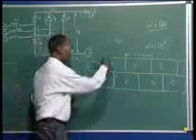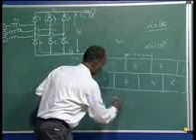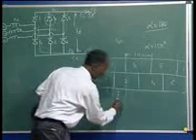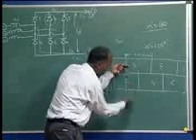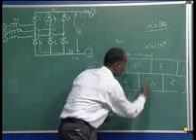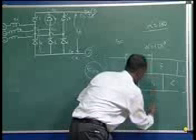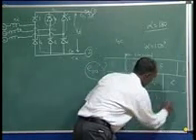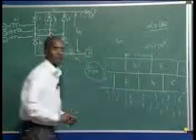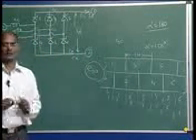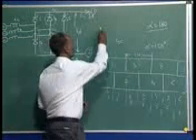You can see here 6 1 was conducting, then 1 2 was conducting. Here you can see 3 and 2 in this zone, so 2 3, here 3 and 4, and 4 5, and again 5 6, and then we have reached the same here. So this was the 2-valve conduction case when U was 0.